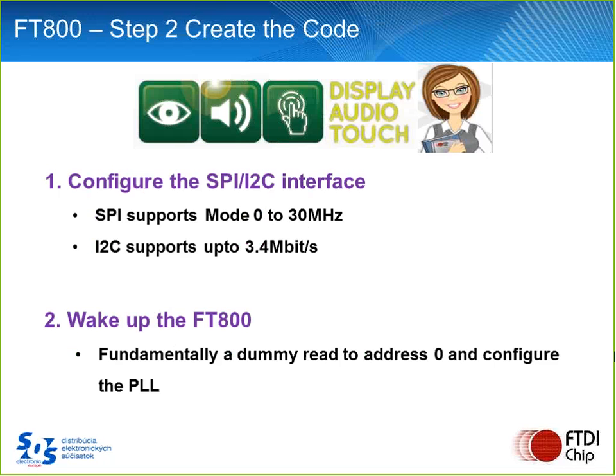So, the next step would be to wake up the 800. It's basically a dummy read to address 0 to configure the PLL, start the clocks, and the chip will come to life.